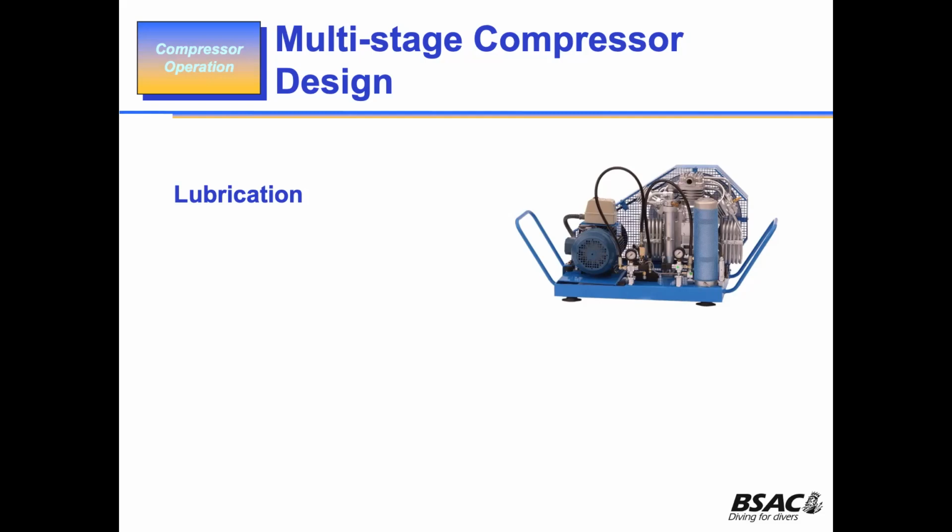The other thing about compressors is most compressors use a non-carbon based oil, a synthetic oil, so we're not going to introduce a carbon based oil into our air system. Now the prime movers can be all sorts of things, but basically on small compressors they're little petrol engines or single phase motors.